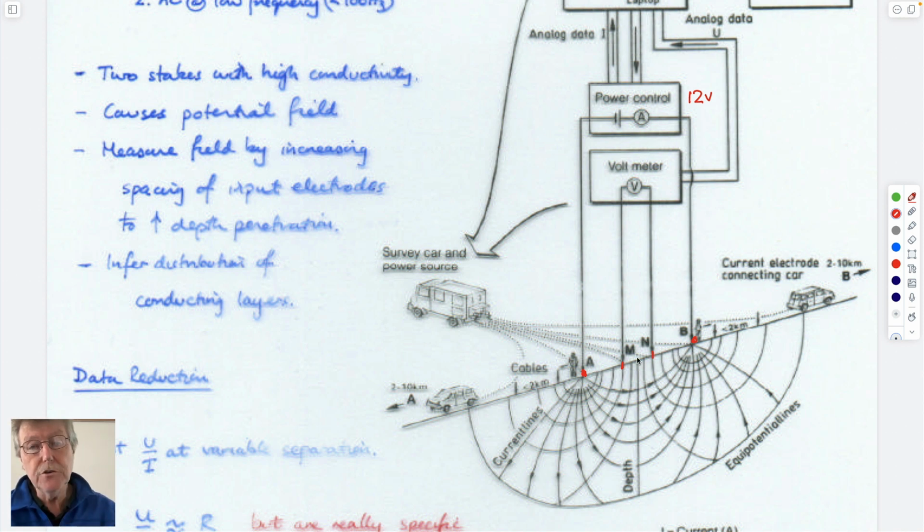So what you could do is use that measurement of the potential drop between those locations, and take this to be able to have this array of these individual components and physically expand it. If you take A and B and you double the separation between them, and you double the separation between M and N, then since you're sampling, you could imagine that sampling between these samples the intermediate area between them.